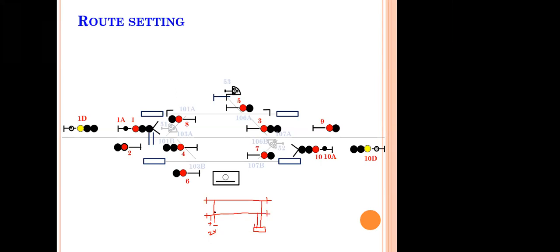When there is no short here and the rails are clear, the track is clear, the positive flows from the positive rail to the relay coil and comes back to negative. Exactly what Mr. Solomon was explaining yesterday. And this is how the track relay energizes. The front contact of the relay I will use for the information that the track is clear.